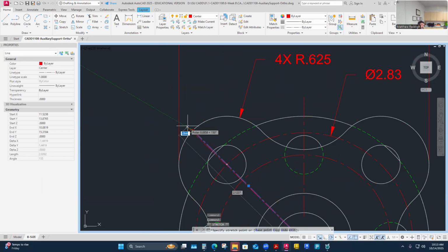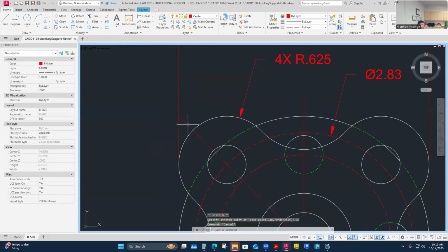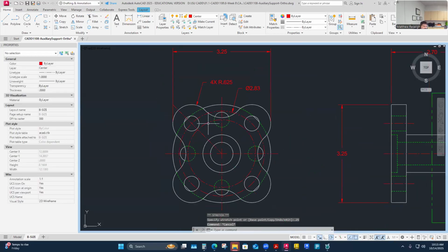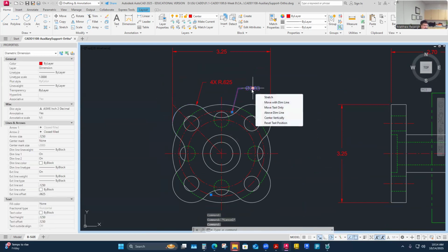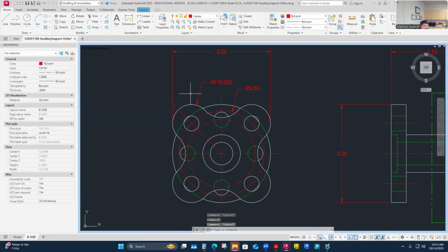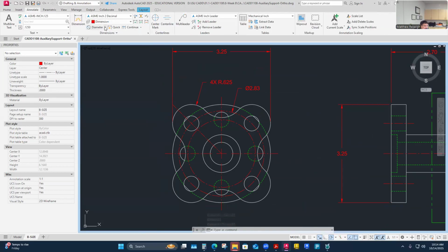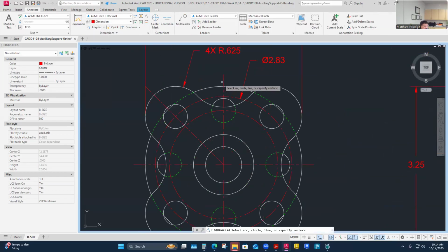And then from here, maybe I need to go like 0.25. This is going to be one to base a dimension off of. Maybe I'm going to crowd this and I'm going to have to move this, but the dimension I need now is for locating this radius only. I've got size. I've got kind of another location here. It's that far out from center axis. So the other location I would need is the angular measurement from this that I'm going to call a control to this.